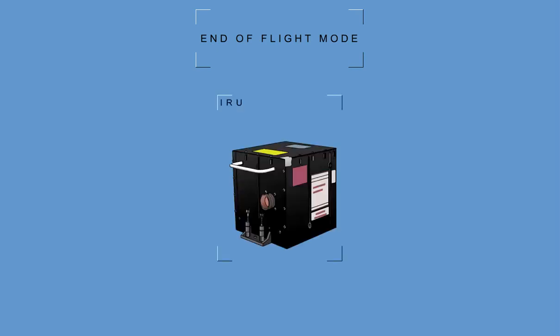End of flight mode. This mode is performed in conjunction with the navigation mode. The micro IRU automatically enters this mode after landing when the airplane has been motionless for a period of 5 seconds. The end of flight mode stores navigation performance records, auto-calibration data, and other miscellaneous information after each flight.